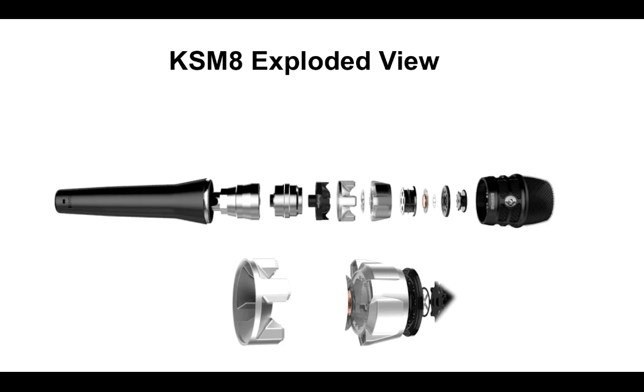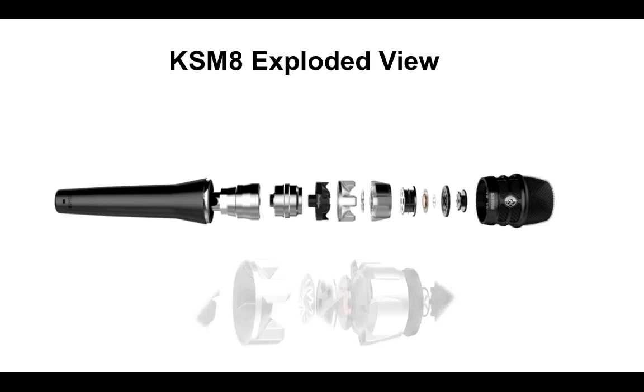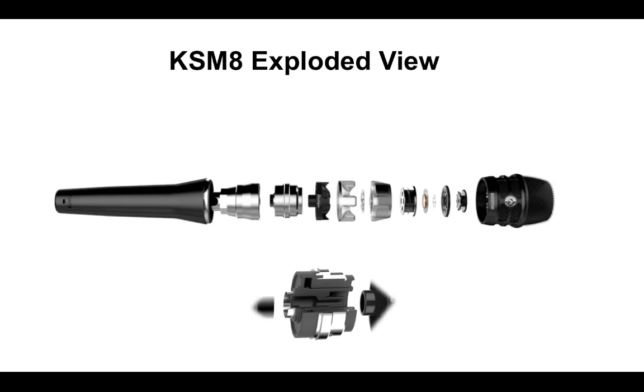It survives ridiculous amounts of torture, actually. It was a completely new to the world laser welding process. We couldn't laser weld it from the outside because of the geometry, so we had to laser weld it from the inside, and these little mirrors shine this laser and seam the two parts together in each of those tubes, which was a totally new thing for us and our supplier. And then there's a pneumatic shock mount in this microphone as well.